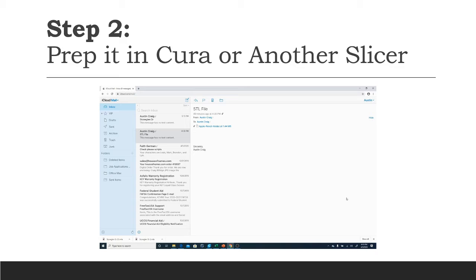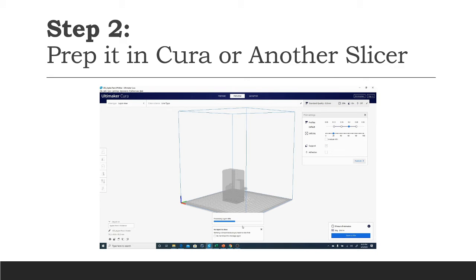Alright, now that it's completely finished slicing, we're going to see how long it thinks it's going to take, which is almost perfectly accurate. So here it shows a little over 9 hours, which is great. And the biggest thing I always recommend is previewing it. So you just click preview, it's going to process your layers. And this is pretty much what your printer sees. So it's always good to check everything and make sure your printer is going to see the right thing.